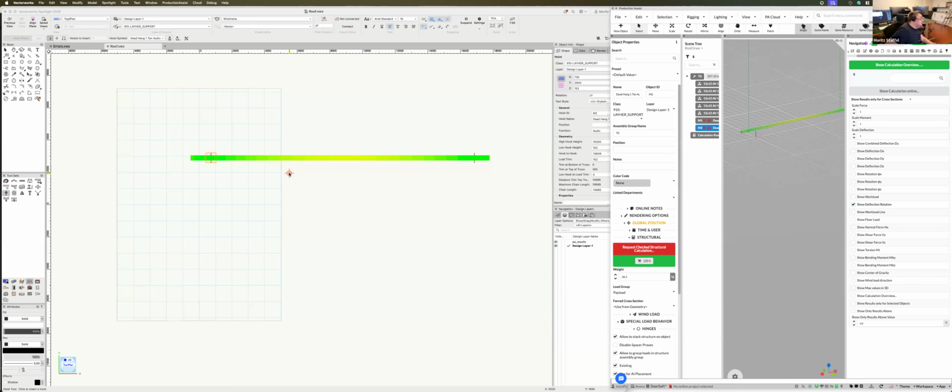So US trusses are rated L/180 or L/160, depending on the choice of the manufacturer, based on how much they are allowed to deflect. So the change that we have with this is that the deflection limit is now basically showing you the deflection limit.